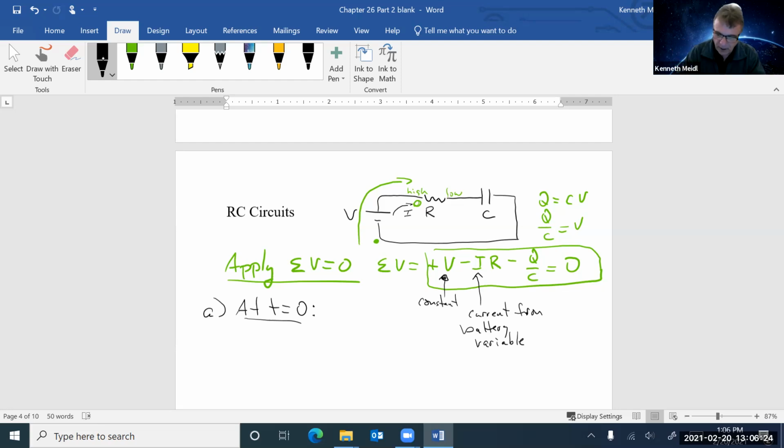So it's variable from I0. Let's write it that way. I0, your initial current, and it's going to go all the way to 0, and that's when the capacitor is full. Okay, so I here is not a number, it's I0, whatever that initial value is, and then it goes down to 0. And so it gets harder and harder to keep putting more charge out.